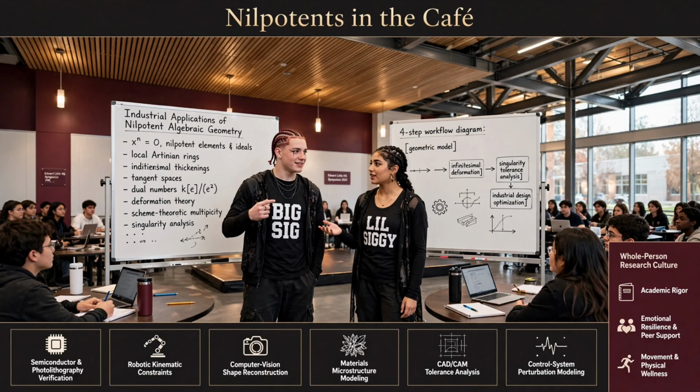In advanced models like SAFT, you have to account for hydrogen bonding. These are highly directional, short-range interactions where molecules physically link up and pull on each other. Like a water molecule. Exactly. The mathematical contribution of these bonds to the Helmholtz energy relies on calculating the fraction of non-bonded sites in the fluid. But calculating that fraction is a paradox, isn't it? It's an implicit equation. It is entirely implicit. The answer depends on the answer.